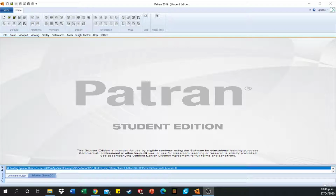For this workshop, four models of the same system are going to be created: a hex 8, a hex 20, a TET 4, and a TET 10 element model. This involves creating geometry from which the meshes are created. The same constraints and loading are used for each model. The results for a linear static analysis for each model are compared.